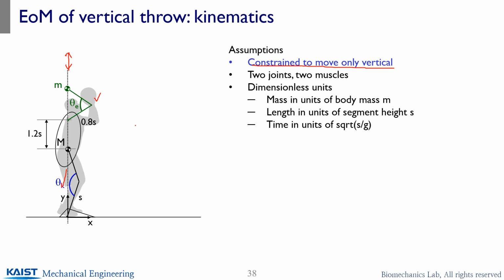And we could set those model parameters based on human observation measurements of body length, height and so on. Those are the numbers we have observed from statistical analysis of human body parameter values. The angles at the elbow and knee joints will take the role of determining the joint torques. And the state variables: there are two masses, at the center of mass and the ball, so the vertical distance from the ground will be the two state variables in these equations of motion.